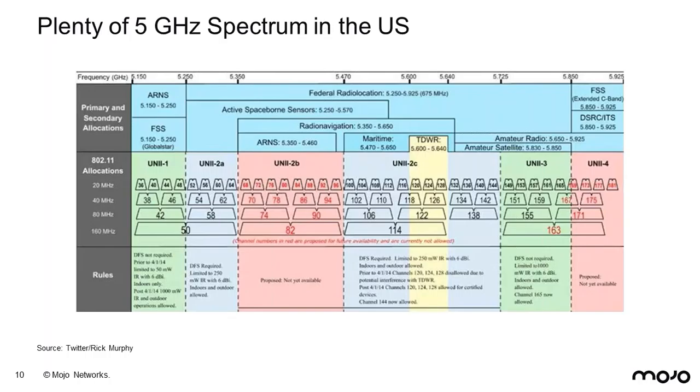5 gigahertz. Wow. One of the most controversial topics you have today in Wi-Fi, and if you go on Twitter and follow people in the space, you'll hear them debating whether or not to use 80 megahertz. Like never use 80 megahertz. Or well, I don't hear anyone saying always use 80 megahertz, but I certainly hear people saying never use 80 megahertz. I just want to point something out.